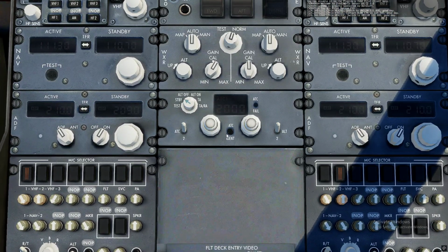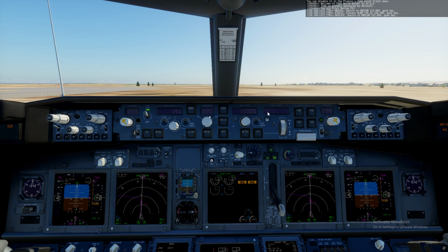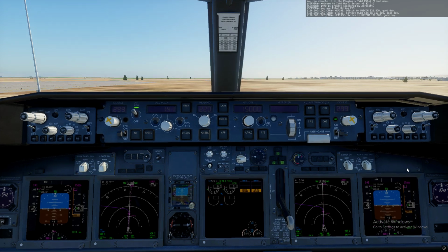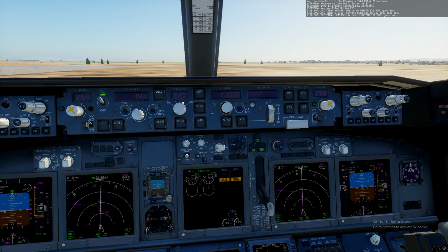Okay, so before we forget, let me set the squawk as the ATC advised. My squawk was 6703. I noted it down. Whenever you are taking clearance, it's better to note it down. 6703. And I turn this knob to TARA. Okay, continuing here. Runway heading set here, initial climb, flight director. Our QNH, which is the pressure, is 1010. I control it from here. 1010.